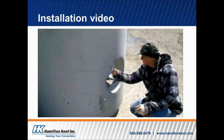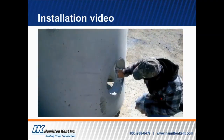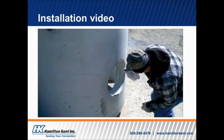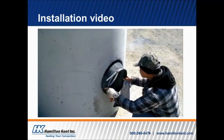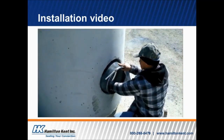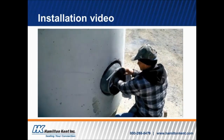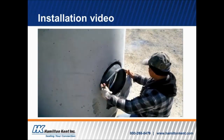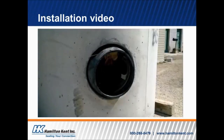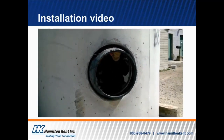I'm going to show a short video here. It starts off with him wiping down the inside of the hole, which is important. We recommend that. So you wipe it down just so there's no debris, and then you put the connector in and line it up so that hoop is roughly about the middle of the manhole wall. And once you have that straight, then from the inside of the manhole or from outside and reaching through, you can then tighten that into place.